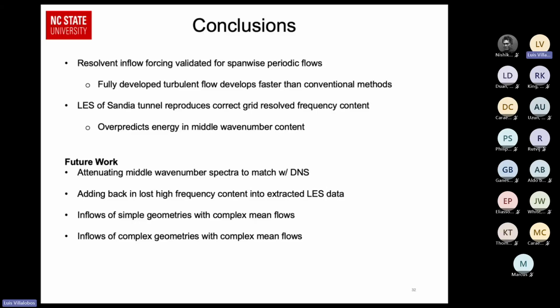We applied this method to large eddy simulations of the Sandia Mach 8 tunnel, and we showed that we were able to reproduce the correct grid resolved frequency content, but we do overpredict the energy in the middle wave number content. Future work: trying to figure out why we're bunching up energy in those middle wavelengths and trying to attenuate that is something that we'll be looking into. Again, maybe the subgrid scale model will do something to help with that.